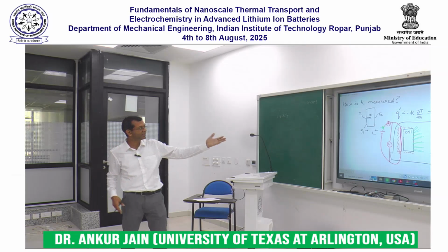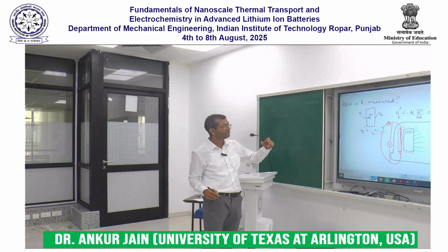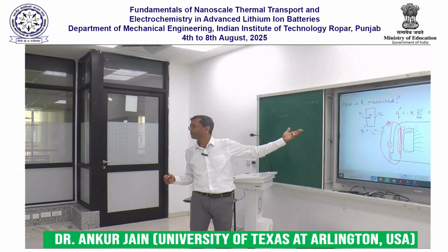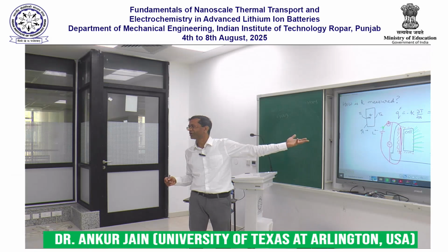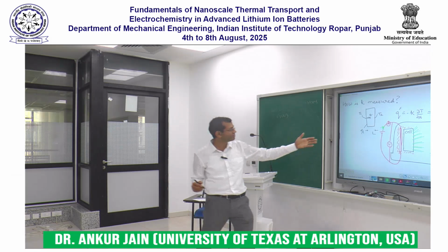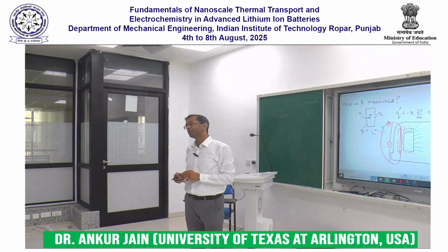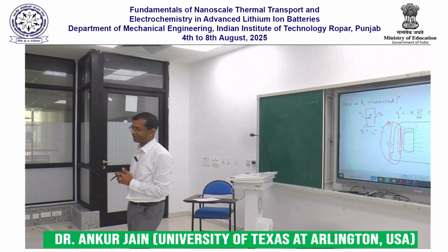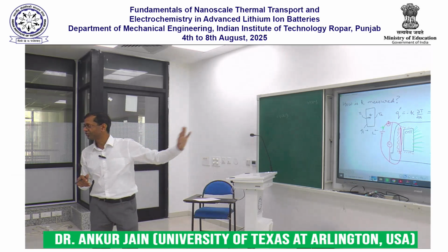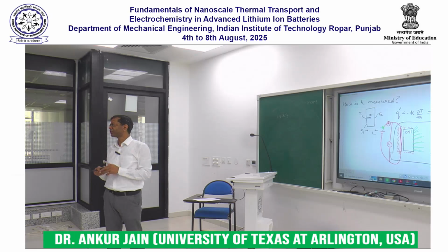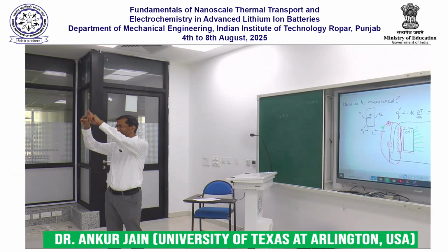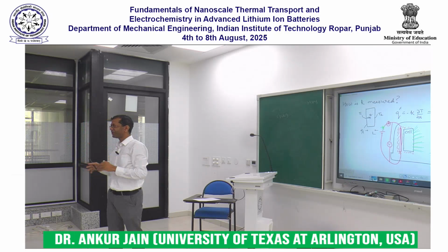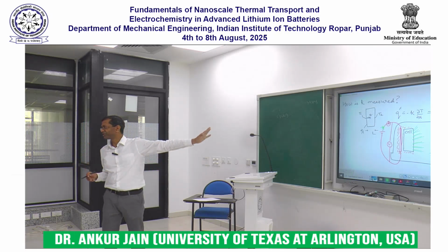Because, for example, in this case, we forgot how we are going to measure the temperatures of the thermocouples. There are these maybe 10 thermocouples. How do you plan to measure the temperature of these thermocouples? So we need a proper data acquisition system to measure those temperatures. Hopefully you will use software like LabVIEW and make a nice GUI, have nice little plots so that you are monitoring the temperatures of these cells, right?